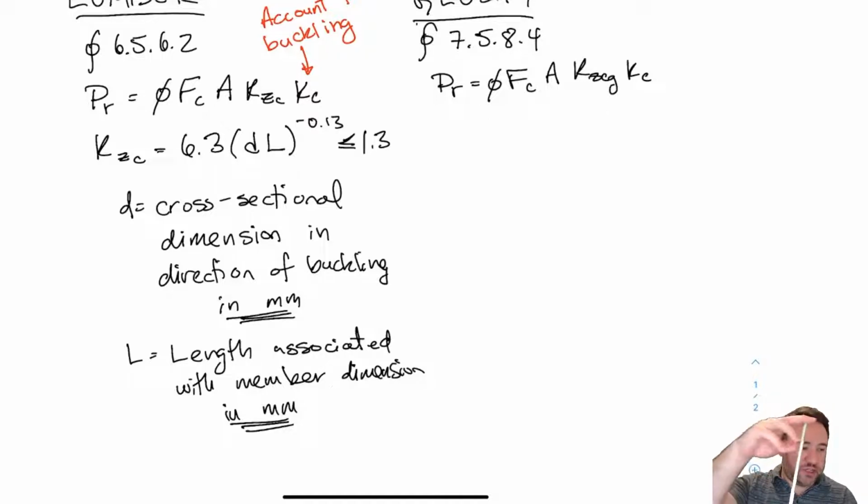When I do this kind of buckling, which is the weak axis buckling, right? I'm going to use the weak dimension. So I'm going to use the thickness for D. In this case, it's a few millimeters, but for a piece of wood, it's whatever it is. So again, if I'm trying to calculate my strength, including buckling in the weak axis, then I'm going to use this thin dimension. The buckling is going this way, and this thickness dimension also goes this way. That's how I remember it.